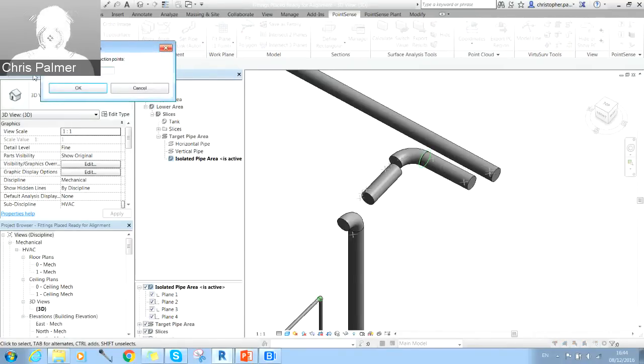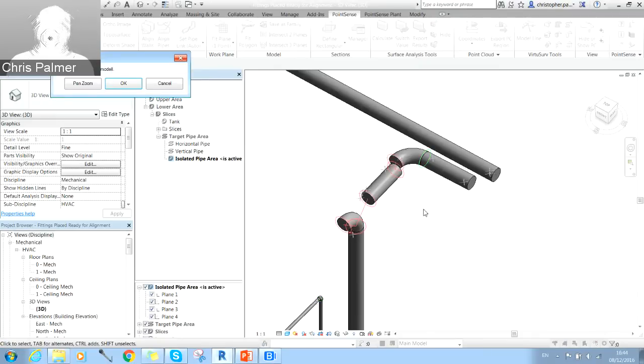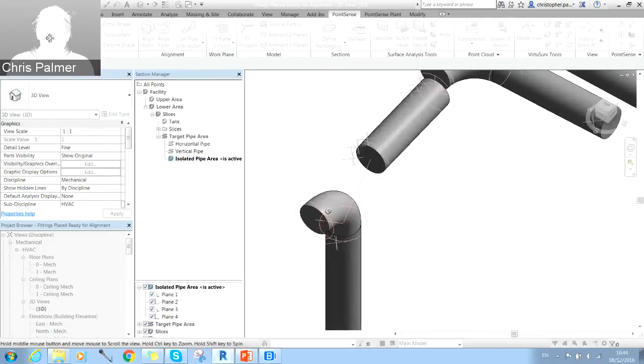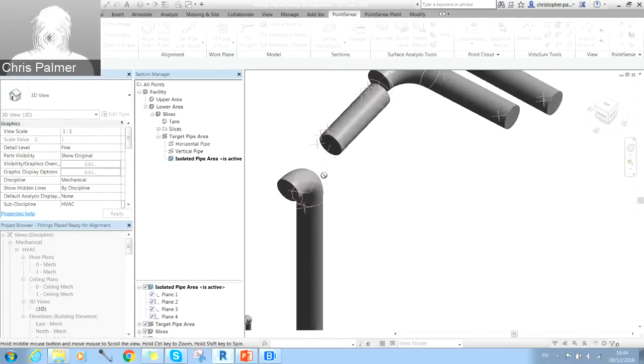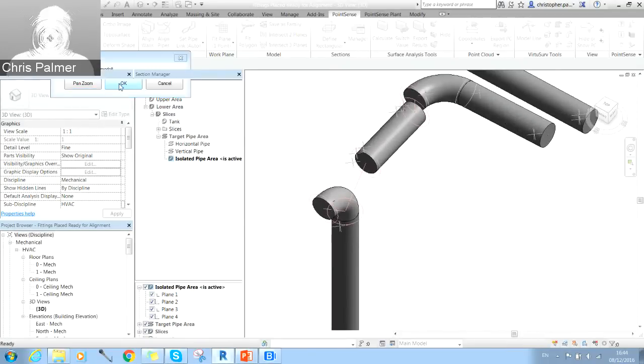So what I'm going to do is run the set pipe link auto tool, and give it a nice big search radius of 600 millimeters. If we run this auto link, you'll notice now it finds those additional links between the pipes. It's actually found this one slightly incorrectly, so we'll see what comes from this. But if we go to, oh no, it's just graphical. So let's go and press OK to that.